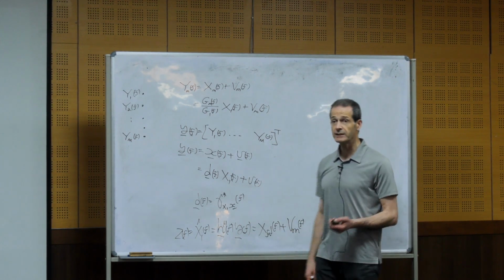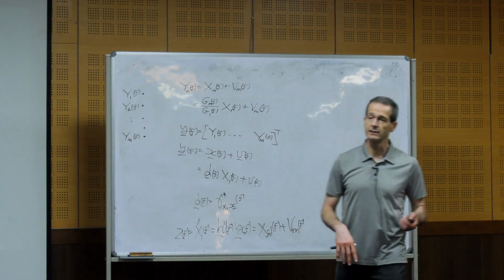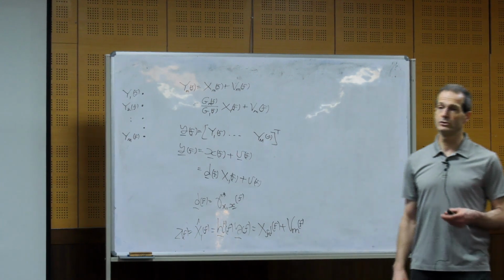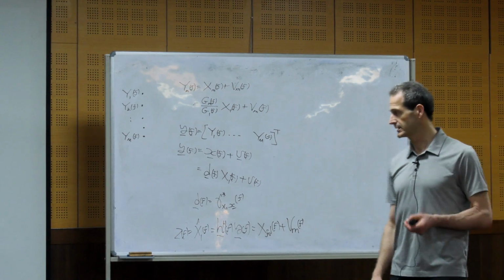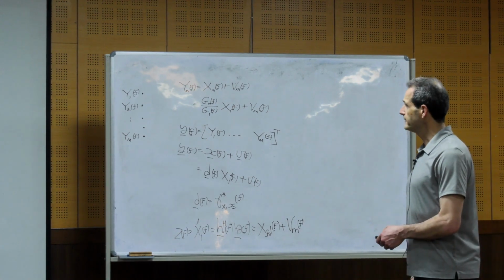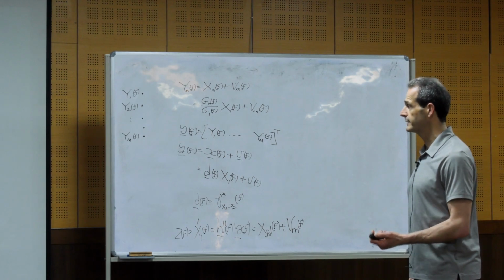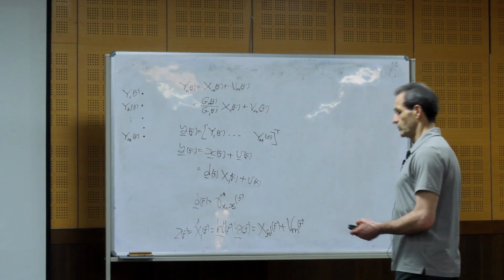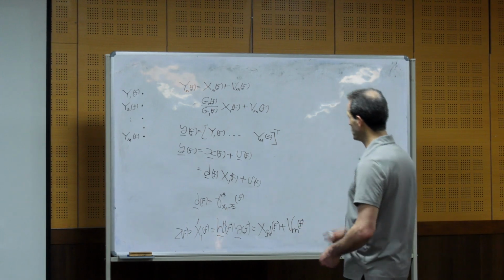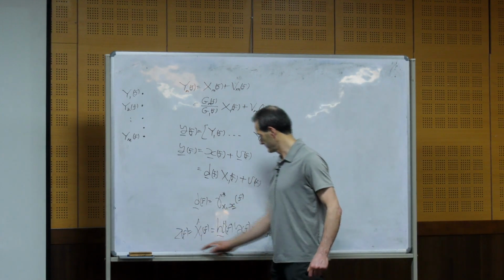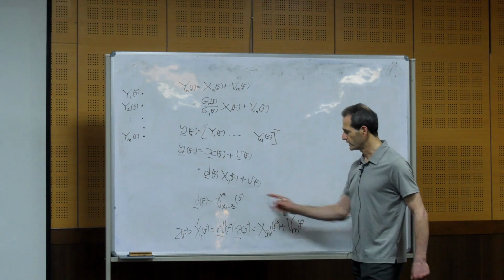So this is the distortion. As we know, it's similar to what we defined for single channel frequency. And then we can also define the mean squared error, narrowband and broadband, which is the mean squared error between the total estimate and X1.